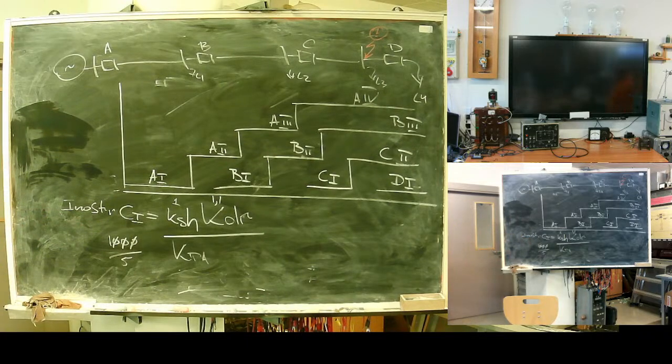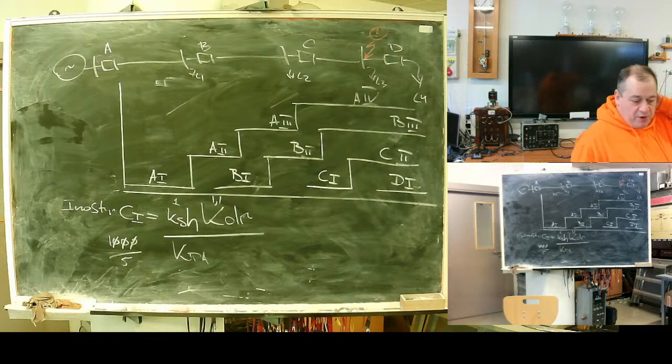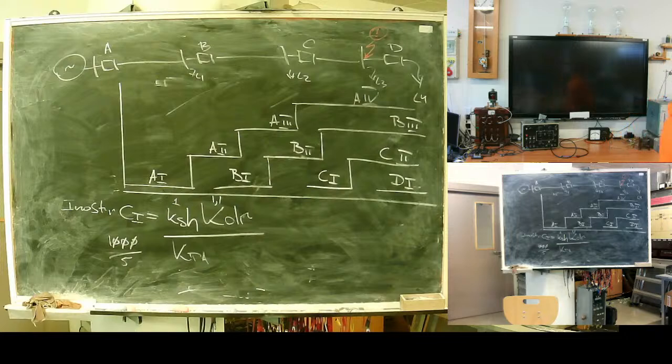There are modern relays with old style where you program in amps as the ampere meter shows, or relays that are programmed in primary amps. This means that you write 1000, but transformers are programmed as separate settings. Read your manual carefully on what you need to input, secondary amps or primary. Nowadays, it's just a question of style.